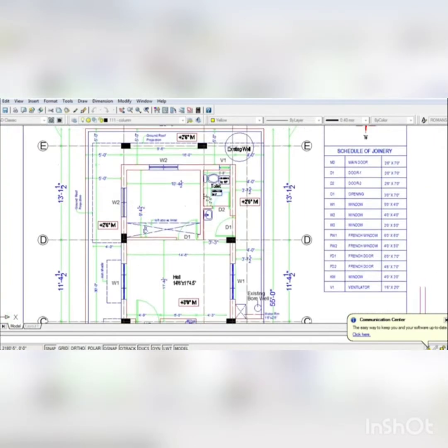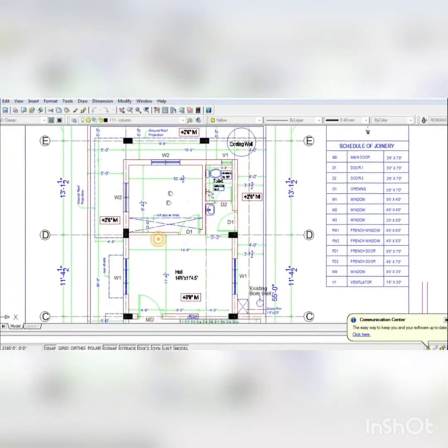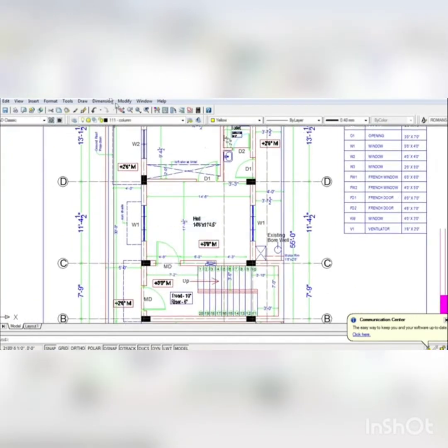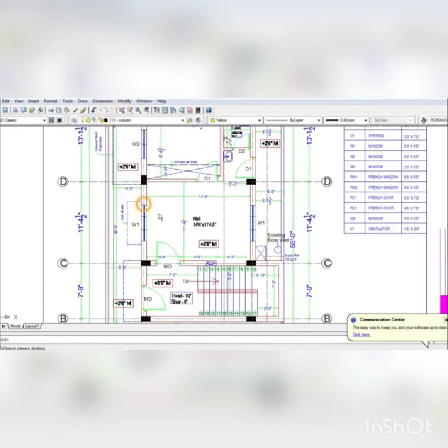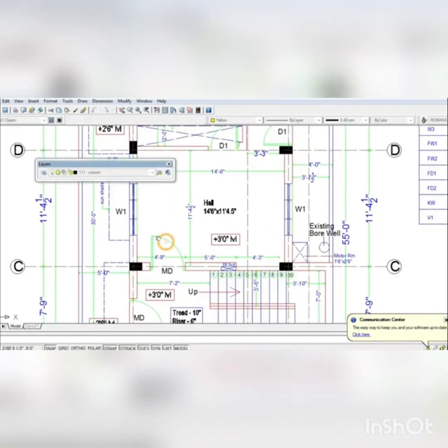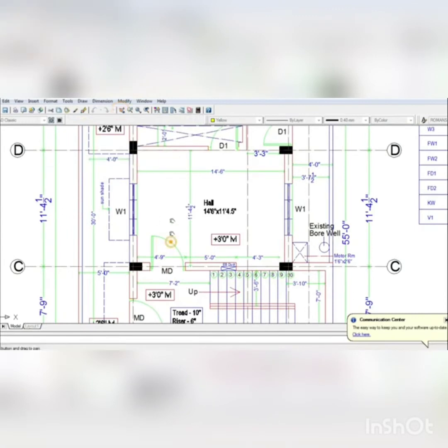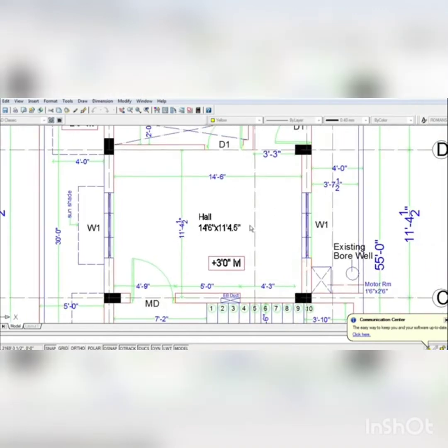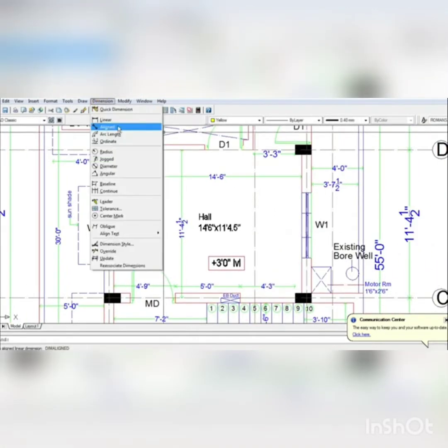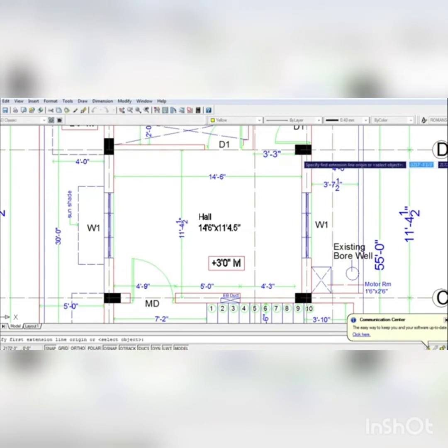We have to know where to place our windows in the room. In such cases, if no dimension is given, then it is understood that the windows are to be placed at the center. If, based on the elevation or some other requirements, you want to place your window at the 1/3 position, then you need to give the dimensions of the window.